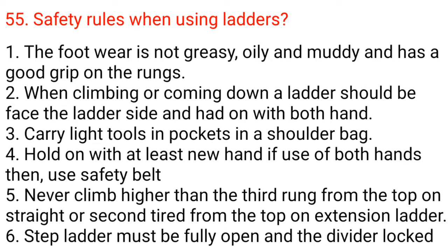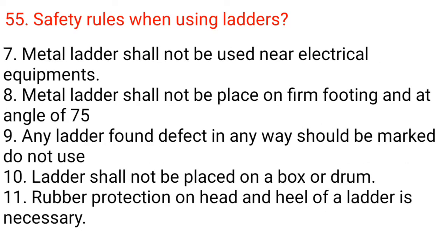5. Never climb higher than the third rung from the top on a straight ladder, or the second rung from the top on an extension ladder. 6. A step ladder must be fully open and the divider locked. 7. A metal ladder shall not be used near electrical equipment. 8. A ladder shall be placed on firm footing and at an angle of 75 degrees. 9. Any ladder found defective in any way should be marked do not use. 10. A ladder shall not be placed on a box or drum. 11. Rubber protection on the head and heel of a ladder is necessary.